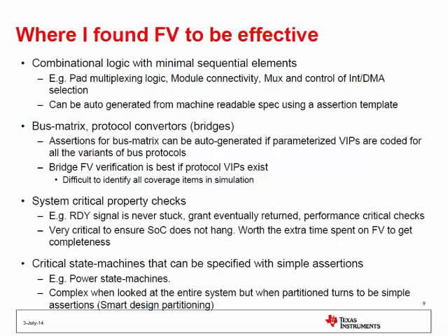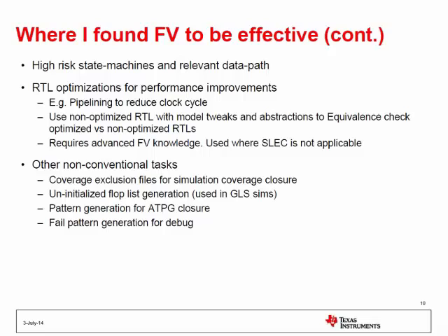Yeah, this high-risk state machines, what I mean is the cache and things like that. And I think RTL optimization, the IBM team and the internal team touched upon as sequential equivalence checking. Here again, it is not straightforward SLEC, but you will still see a lot more optimization being done. If you look at industry standard tools, you still have SLEC tools, but some of the tools won't be able to handle some of the optimizations you're doing. So you may have to fall back to your formal verification tool to get some of these things verified.